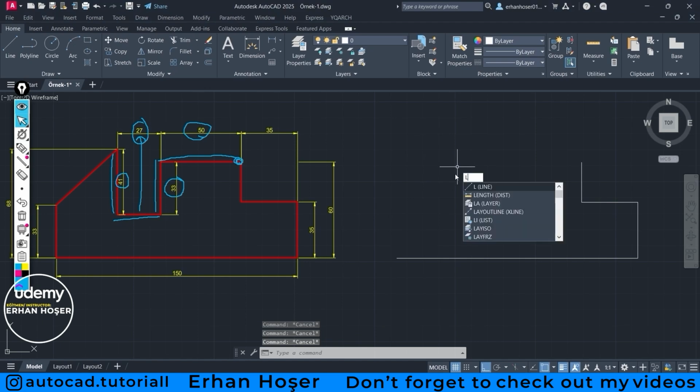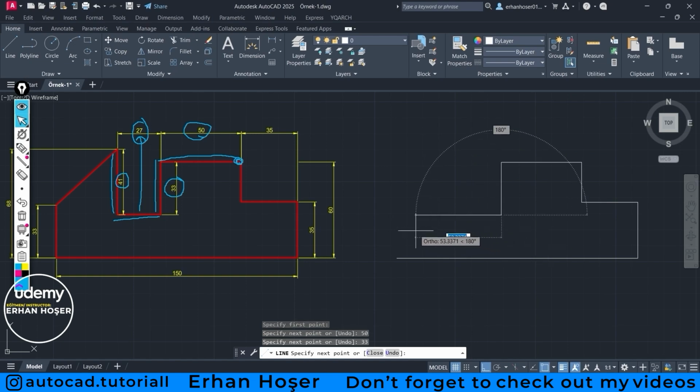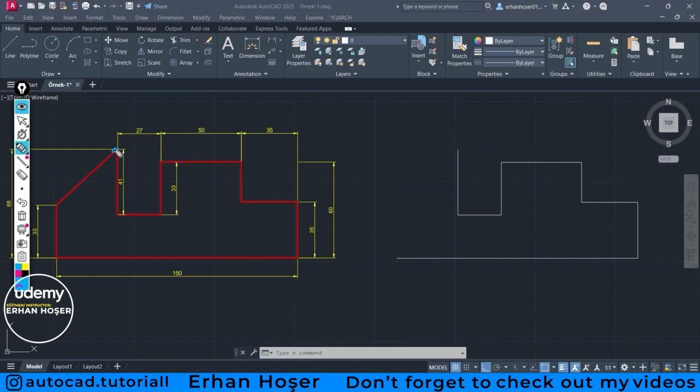Let's draw these immediately. I pressed L, I pressed space. I clicked once on the last point and pulled my mouse. 50, enter. I pulled my mouse down. 33, enter. I pulled it to the left side. 27, enter. I pull up. 41, enter. Now look, we've come to this point.